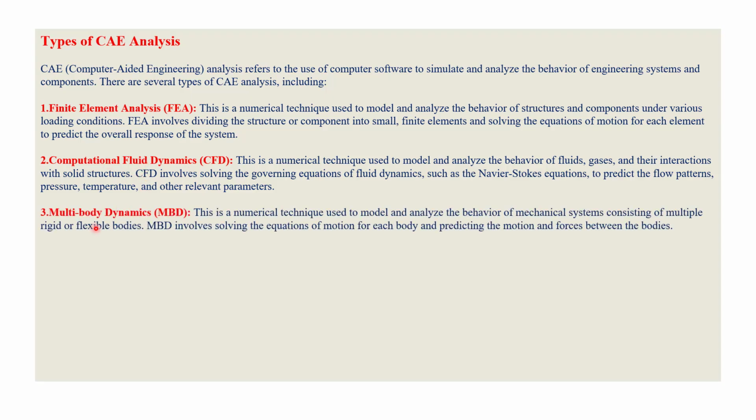The next one is multi-body dynamics, which is also a popular domain, where we deal with the mechanical behavior of components. MBD involves solving the equations of motion, which helps us predict the forces between the bodies and the motion between the bodies.